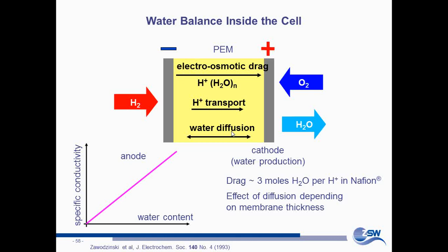So we're still at a one-dimensional look at the fuel cell. You have to keep in mind that fuel cells have at least two dimensions to worry about. So you can operate a fuel cell on unhumidified hydrogen. That's no problem. It's pretty difficult to operate a fuel cell on unhumidified air.